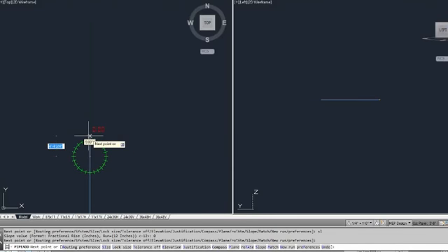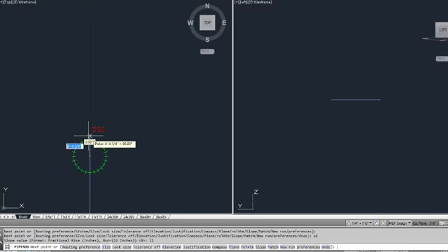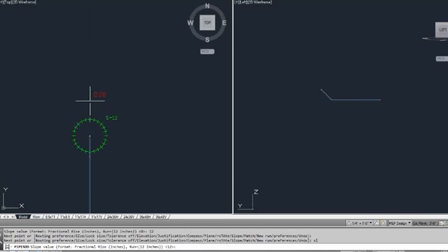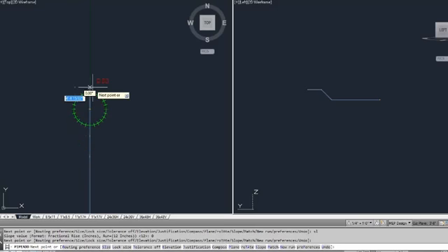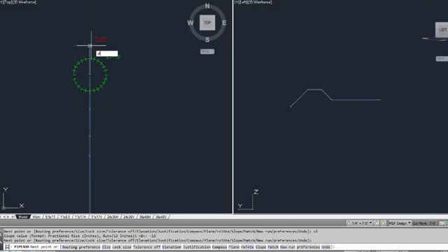Now put in a slope of 12, short little piece of pipe, slope of 0, short little piece of pipe, and a slope of -12. Another piece of pipe, and then a slope of 0.